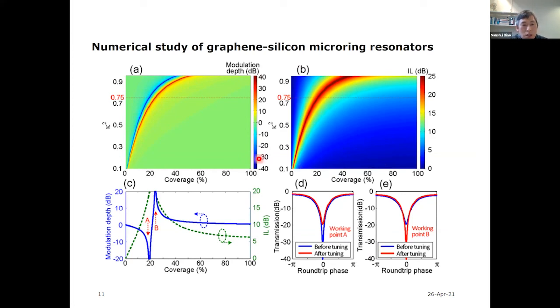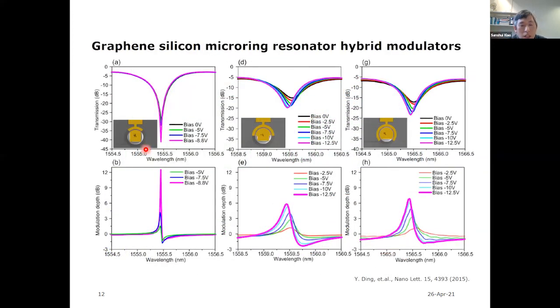So actually, this part is a numerical study of an optical design structure that provides high modulation depth and also improves insertion loss performance. By using E-beam, we can make any kind of structure we want. If we look at this section, this is a ring resonator.